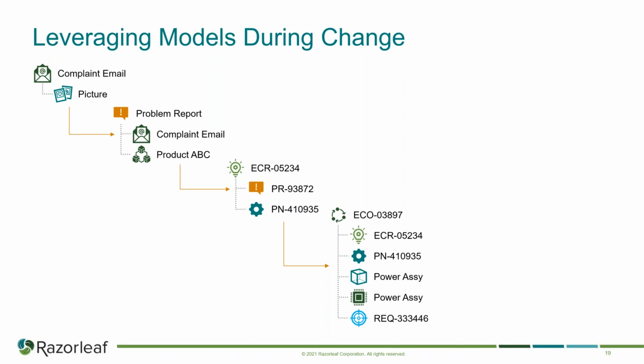Here's the part that's interesting that I want to highlight about all this model connection that we did on the previous slide. We should also be looking at the requirement, right? Because what changed here? If it was okay for the product to get to 170 degrees Fahrenheit, then that shouldn't be burning anybody. But the problem is that requirement that said you can't exceed 170 Fahrenheit was actually wrong. You make something 170 Fahrenheit and you touch it for more than about 3 seconds, you're going to burn yourself. The right number is 140 Fahrenheit.